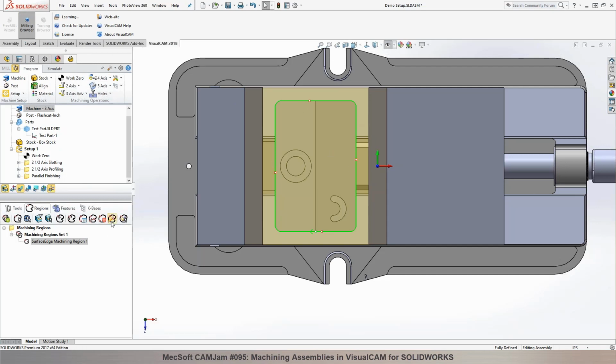It'll place 4 bridge points, and now I can go ahead and edit these bridge points around, and I can specify where these bridge points need to be placed. So what does the bridge point actually look like once it's machined? You can do a rectangular bridge, or you can do a triangular bridge. We'll go into the setup in just a moment.